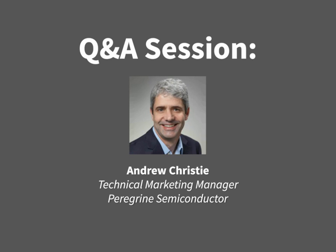Okay, our first question is, what semiconductor process is being used for 28 gigahertz power amplifiers? The 28 gigahertz, I assume. So for 28 gigahertz, we're using Peregrine's Ultra CMOS process. For this application, it's a SOI process, so a CMOS on insulator process.